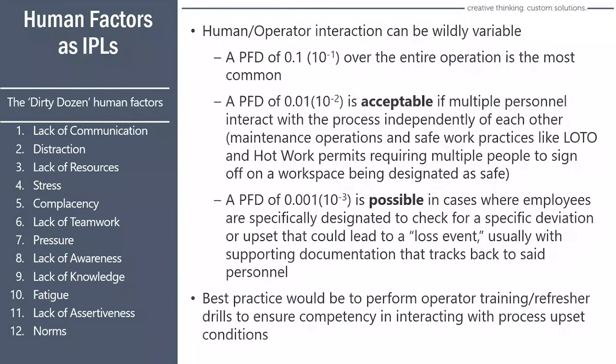And again, this gets back to our reliance, if we have such, on people and the operator's ability to do the job correctly. And how likely is it that the operator is going to make a mistake? Well, unfortunately, of all the PFDs, operators tend to have the lowest reliability.